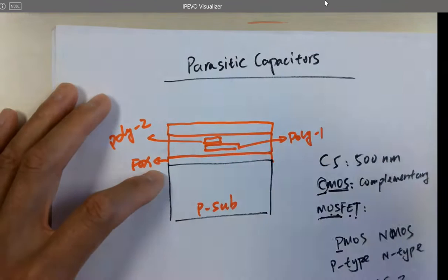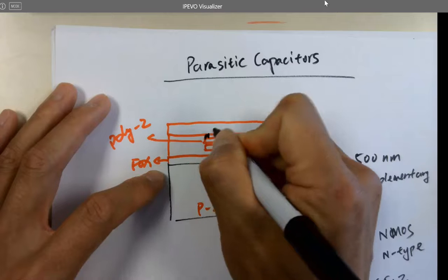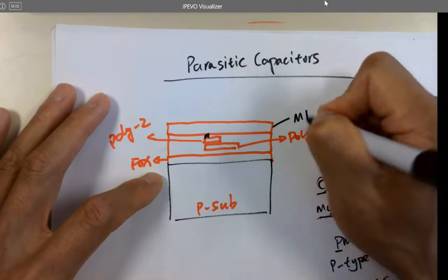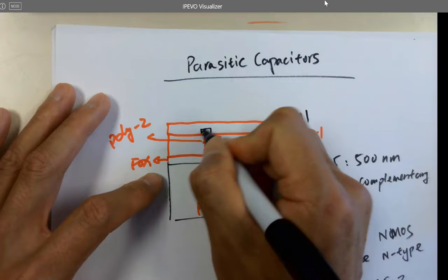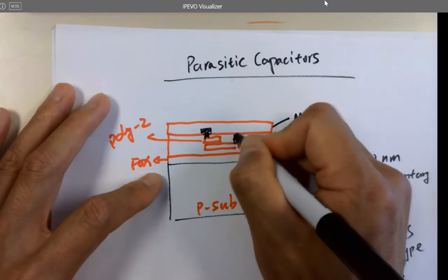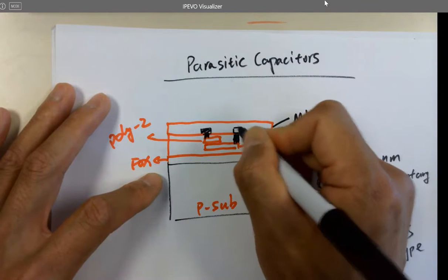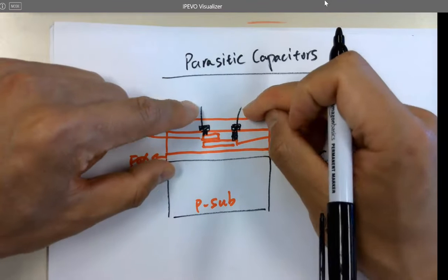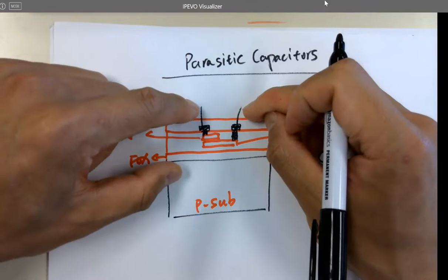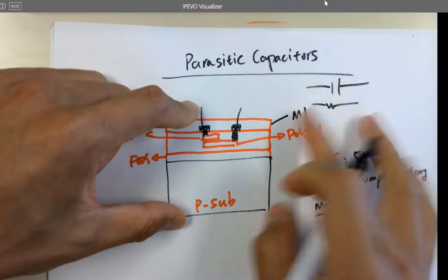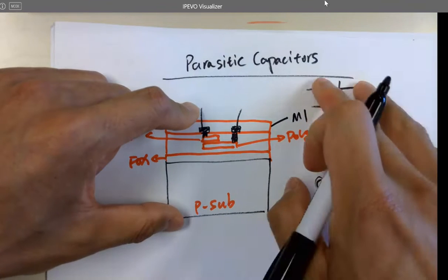And definitely you need vias to connect to where? So what's this layer for? Metal 1. And you need a little metal here, right? And here's a via. And you need another via, drill a hole to the top layer and get a metal 1. So these are the 2 terminals. You saw the capacitors or resistors in the labs, like a capacitor like that or resistor like that. It has 2 terminals for each of them, right?